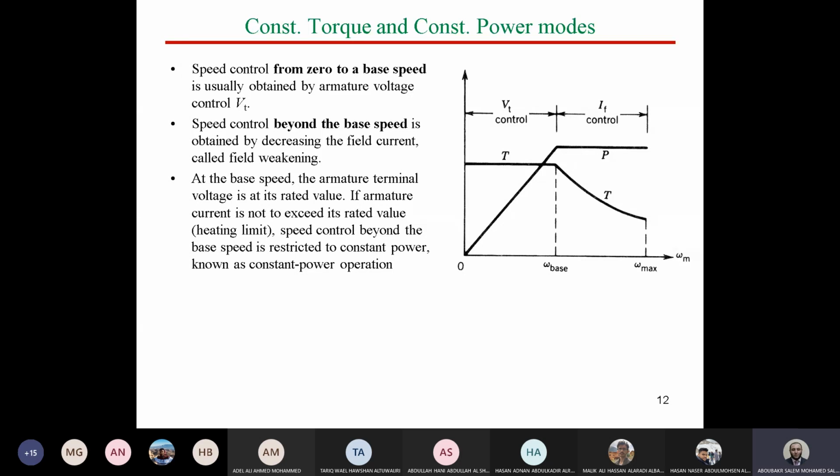One of the best control techniques for DC motors is to keep control in zones. We said that we prefer voltage control, however, we cannot control the voltage over rated. And also, for field control, we do not prefer to increase the field too much, to avoid saturation.